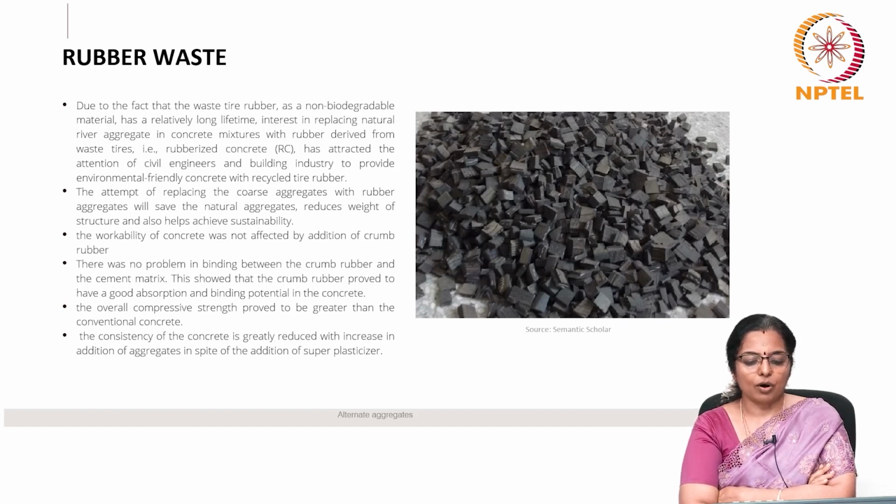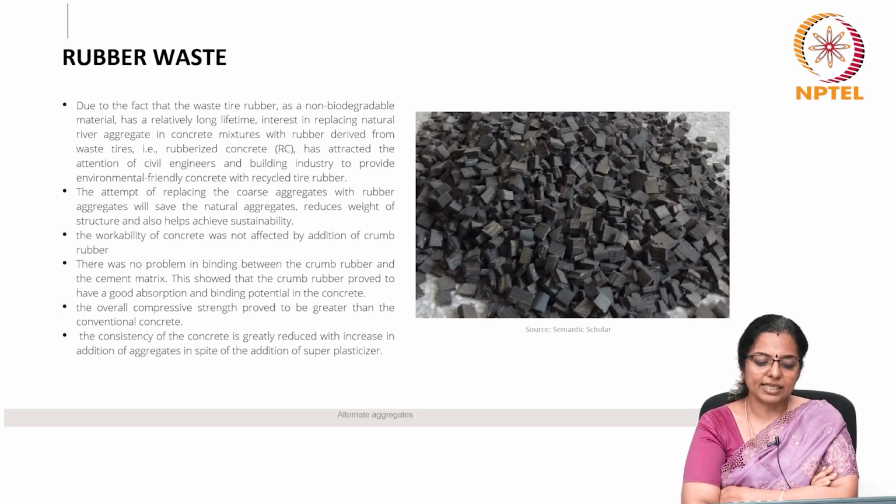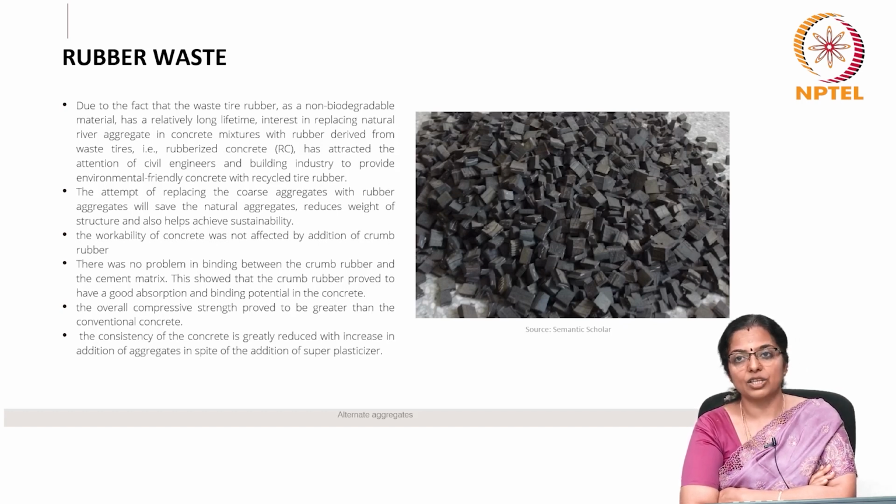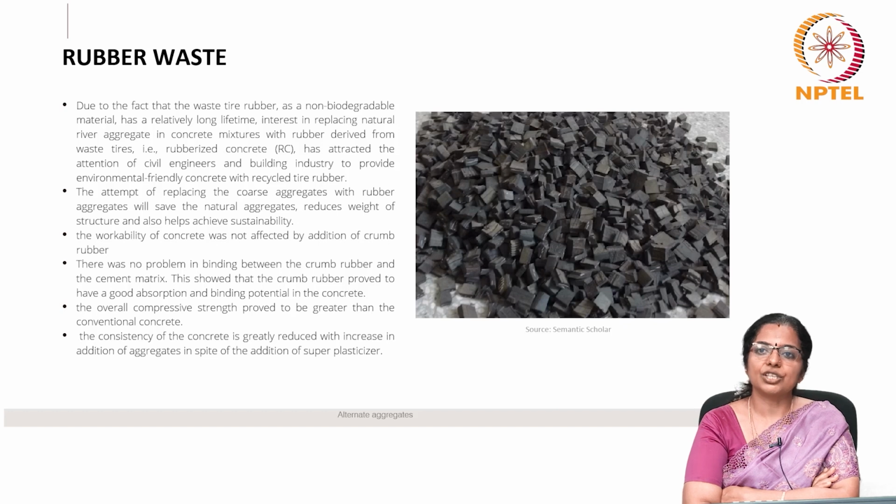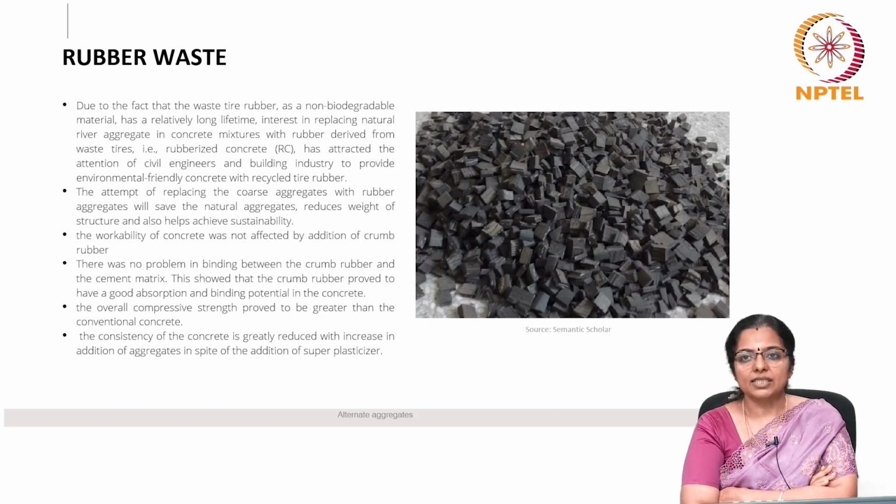The workability of concrete is not affected by addition of crumb rubber. There was no major problem in binding between the crumb rubber and the cement matrix. This showed that the crumb rubber proved to have good absorption and binding potential in the concrete. The overall compressive strength proved to be greater than the conventional concrete. The consistency of the concrete is greatly reduced with increase in addition of aggregates in spite of the addition of superplasticizer.